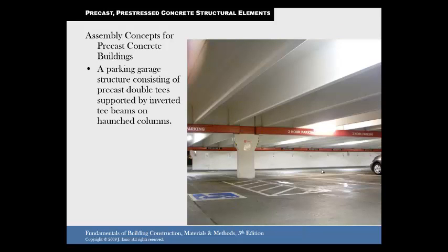There's like an inside of a parking garage. You can see the double T's, and you can see the joint between the two pieces there. And they'll probably fill that with some sort of caulking material. And one good thing on a parking garage too, it doesn't really matter if there's little cracks because it's really an outdoor environment anyway. You'd have to seal it up tighter if it was a building that you meant to be inside.